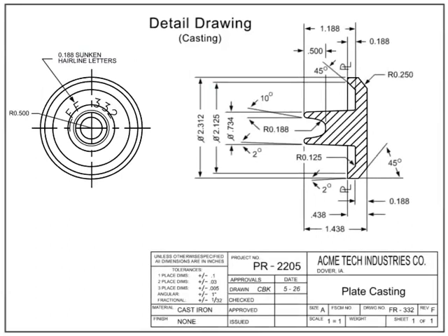The dimensions on a casting drawing are what the foundry or manufacturer uses to make a pattern or mold and are the final cast dimensions of the part. Other information that may be included on a casting drawing are mold lines, datum plane references, and even information on how to best remove the part from the mold.